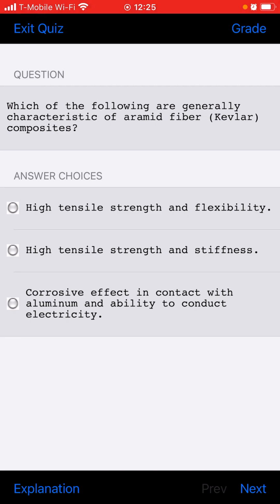One method of inspecting a laminated fiberglass structure that has been subjected to damage is to strip the damaged area of all paint and shine a strong light through the structure.